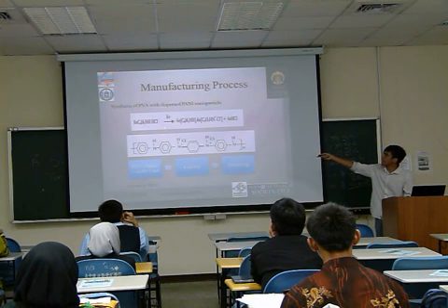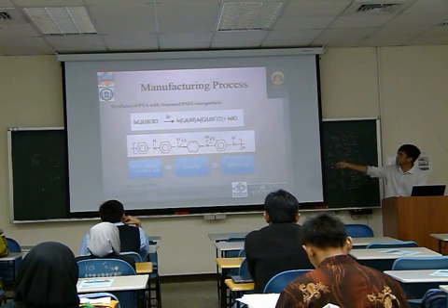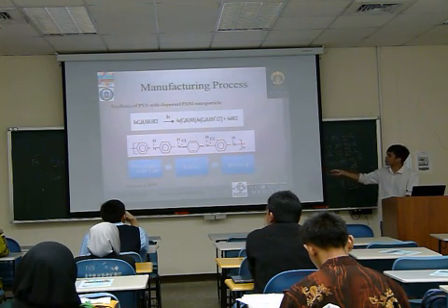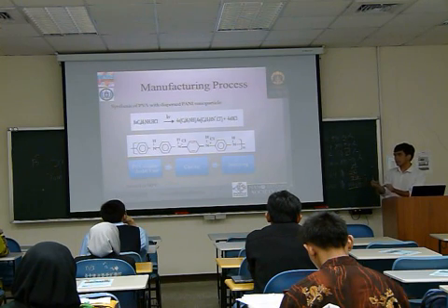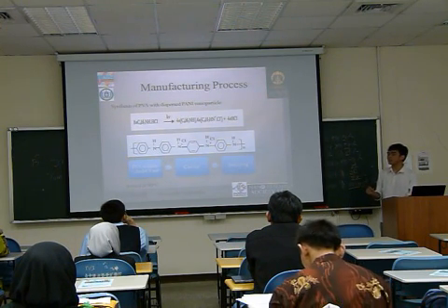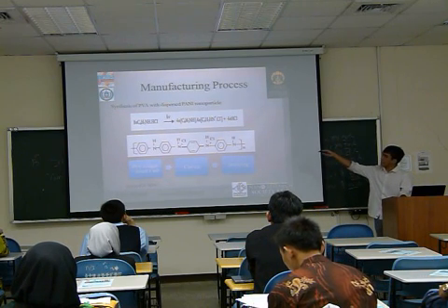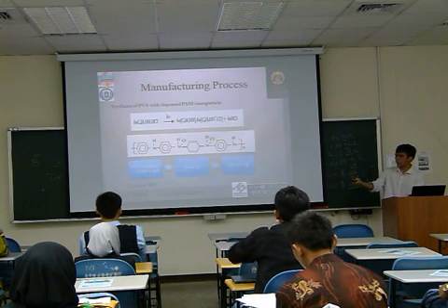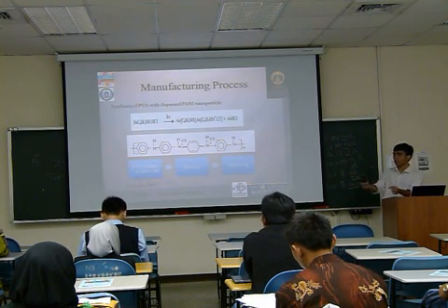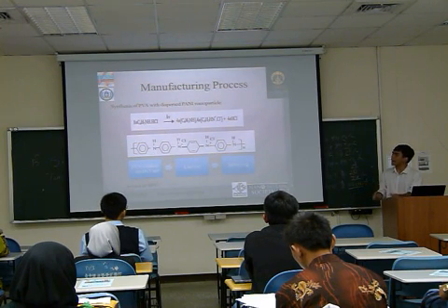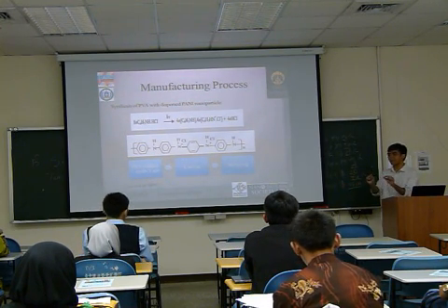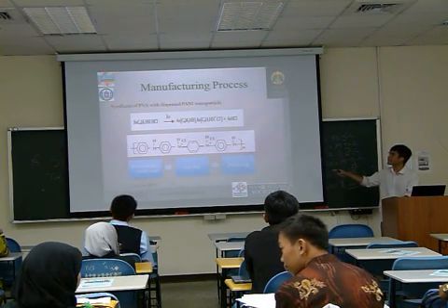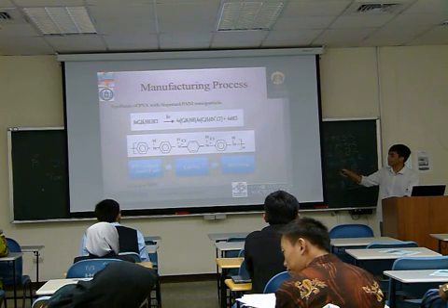This is the polyaniline salt, and we put it into the polyvinyl alcohol solution and let it dry at room temperature. So what we have is a solution containing polyvinyl alcohol and polyaniline, and we cast it. What I mean by cast is we pour the liquid solution into a mold, a thin plate, and let it dry so it forms a thin plate which consists of finely dispersed polyaniline nanoparticles.